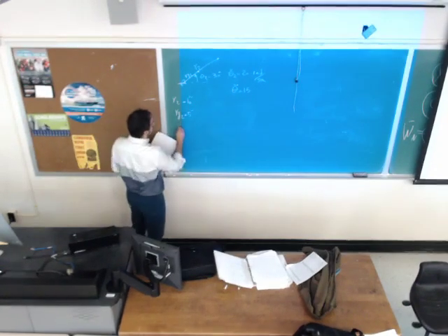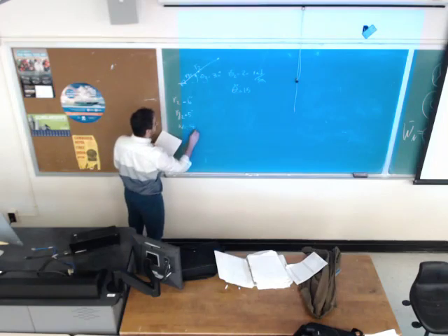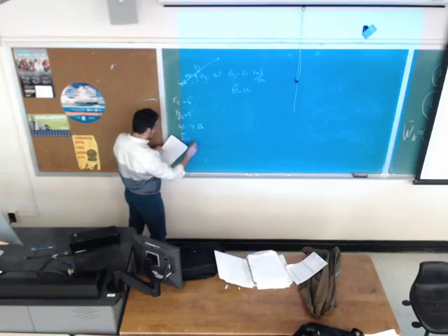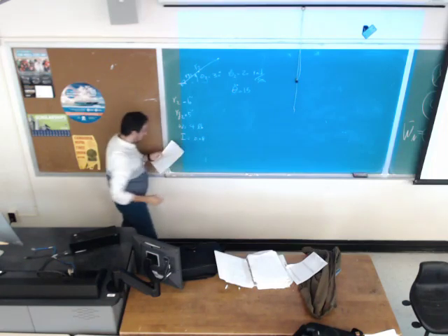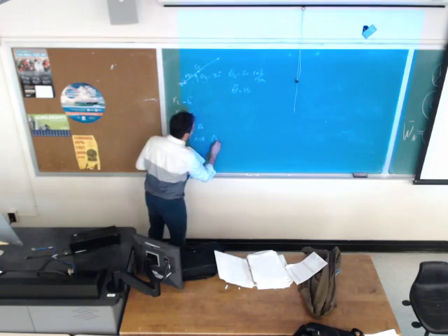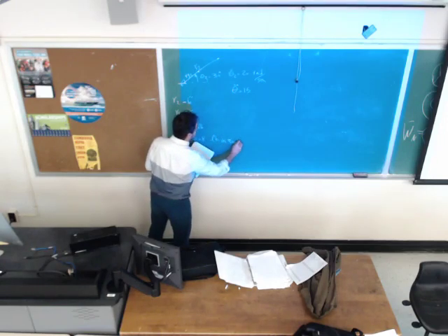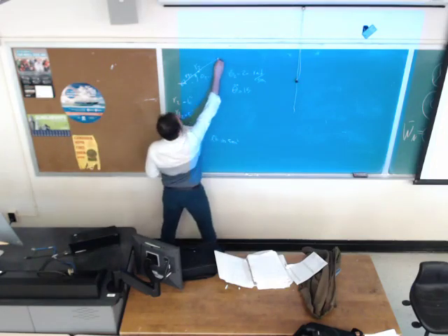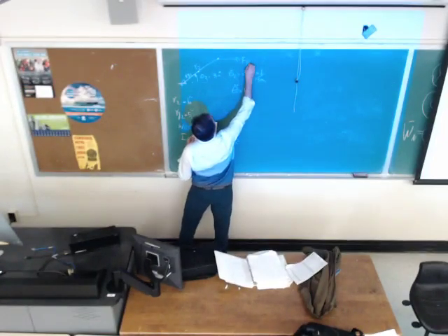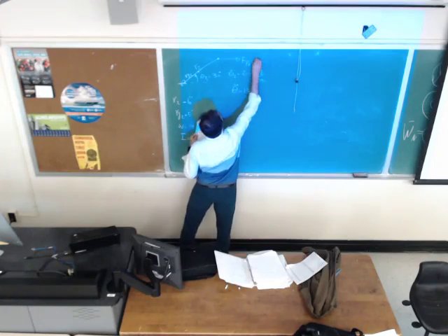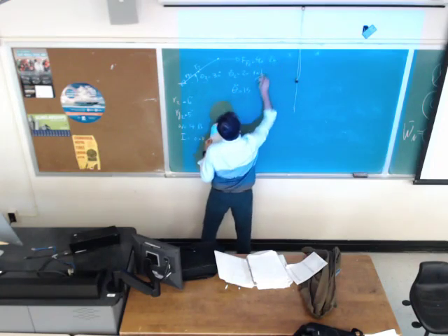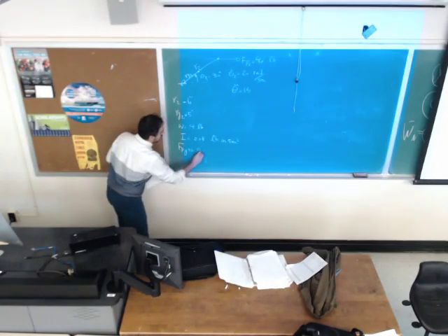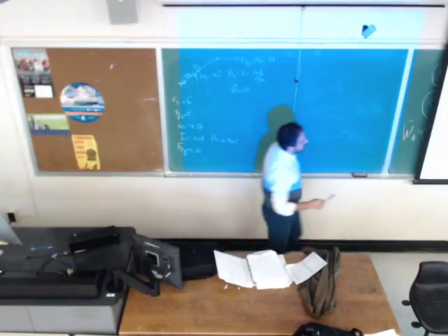The weight of this rigid body is 4 pounds, and the mass moment of inertia is 0.08 pound inch second square. The force in x direction, Fpx, is 40 pounds, and Fpy is 0 pounds. So we don't have any force in y direction.